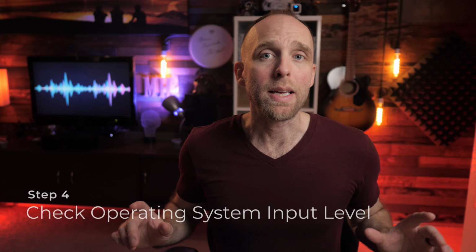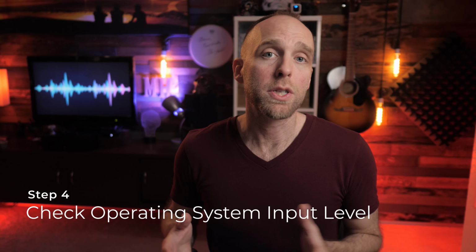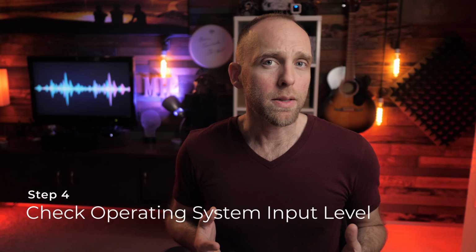All right, step 4, and I'm willing to bet this is something that almost everyone forgets to check, and that's the input level on the computer itself before it gets into any other software or meeting platform. Basically, even when used as a USB mic, the operating system, be it Mac or Windows, has its own USB preamp or input level that we have to check first because it's the next piece of equipment in line after our mic. And if we clip out our signal just as it enters the laptop, then everything downstream of that main input is going to receive a clipped signal.